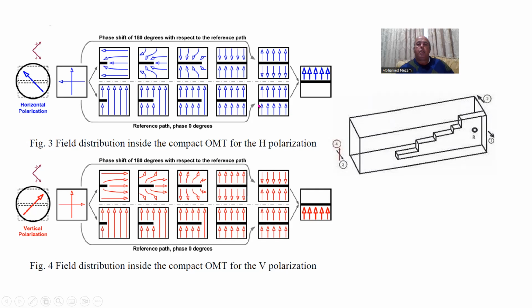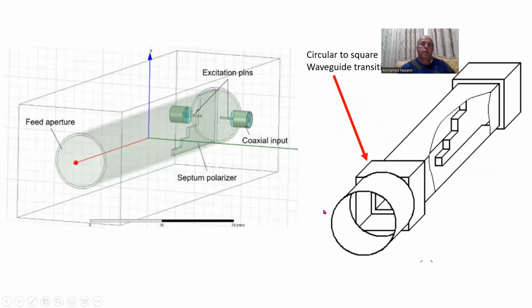And now if you combine these, okay, what happens is that the lower side in here, basically this one with this, cancels out because it's 180 degrees out of phase, while this one is really in phase with that one, and you get that one, okay? So that means that you got that polarization. Now, likewise, you can go in and start tracing what happens to the other polarization, and you'll see that it comes naturally, falls in the separate waveguide, okay?